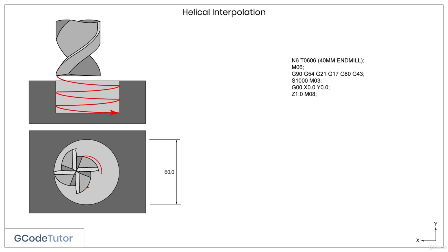At this point, you will know if you set your tool correctly, because rapiding 1mm off the face of the material won't end well if you haven't. Switching over to a G01 feed rate command, I now bring the cutter down to 0.1mm off the face of the material, using a feed rate of 200mm per minute.